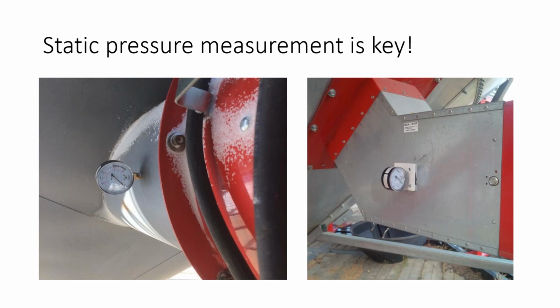With the inverted trough and the rocket, that's not an option because they're self-cleaning. They aren't an enclosed system, so there really is no back pressure when you have no grain in the bin. Ultimately, to get a feel for the performance of those systems, you need to have your tube covered, and then you get a better feel for the effect of louvered area and the impact it has.